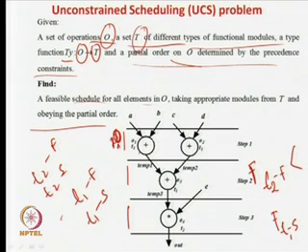If you say that it is 10 nanoseconds and the addition here takes 20 nanoseconds, you will have a problem, because even before the addition has been done, you will come to the next time step, or the clock will arrive. That will be a problem. So, whenever we say that it is 25 nanoseconds, you should ensure that these two operations are done, and this operation is also done. So, who will decide what the time step length is? It is very obvious: the slowest guy in the whole schedule will determine that.